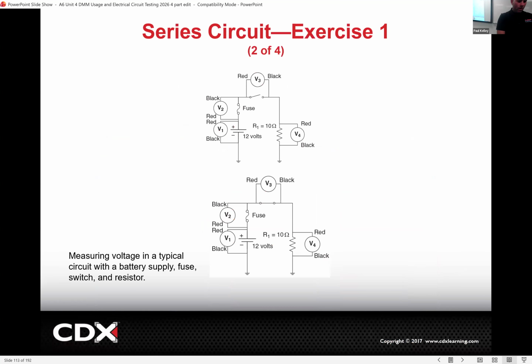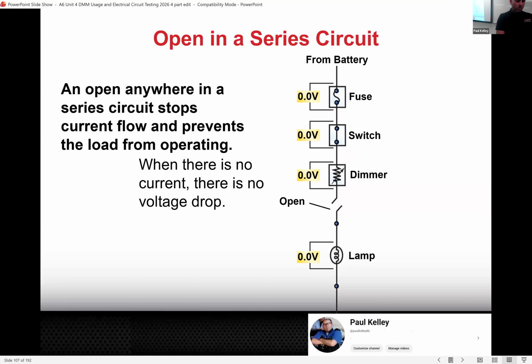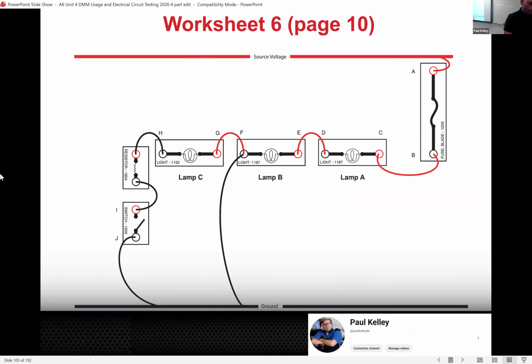I wanted to find a ground-controlled circuit just to illustrate exactly what I'm trying to tell you. Okay, nice. Well, that's a short right there. So if you notice, I made a short, I'll even redraw it. If we make a short from here to ground, do you think that's going to blow the fuse? Because look, the electrons still have to go through the same bulbs. What is it bypassing in its short?